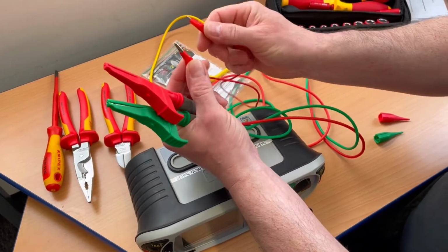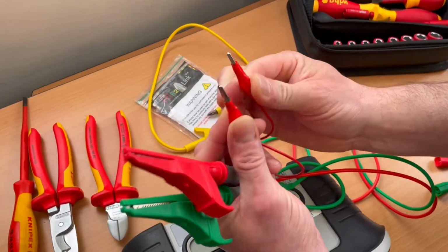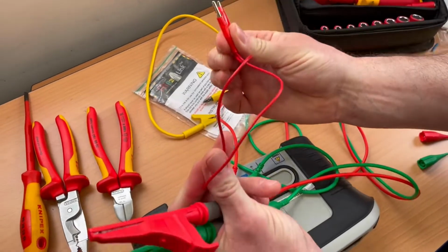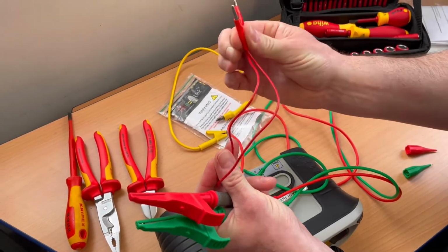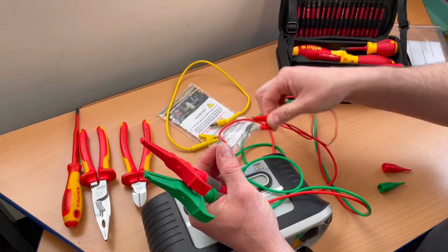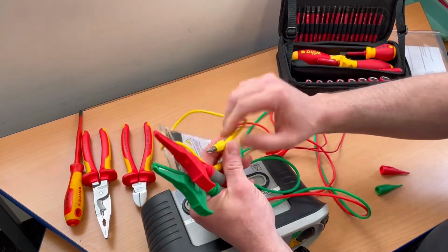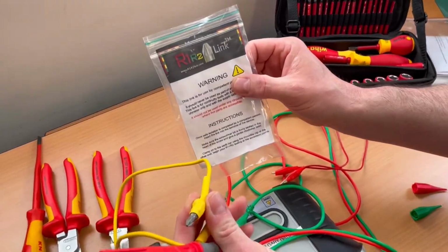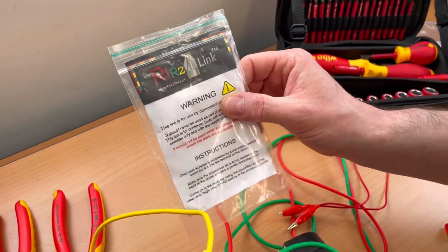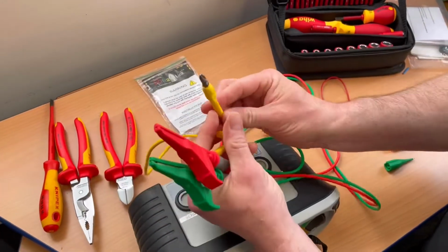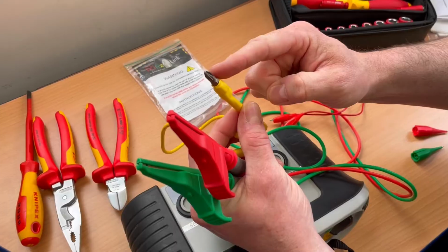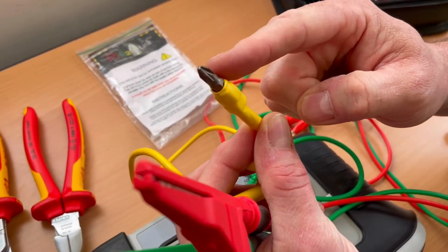And I use those, so I would have to remove the resistance of these crocodile clips and obviously the link here that offers resistance. But I've moved away from that recently and started trialing this, which is our R1, R2 link. Okay, so I've started using this for a college setting especially, because this end here is magnetic and will go onto the top of my MCB for my lighting circuit.